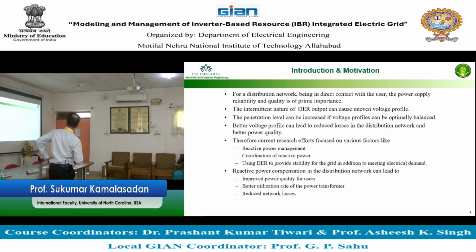Reactive power management is by and large important, for example, for the voltage profile. Now the coordination of the reactive power is also important, especially if the reactive power is coming from the same location. If the reactive power is coming from a few different locations, coordination is not important. Why is it not important? Because we say that reactive power is not global. It's a sentence which we learn. Why is reactive power not global? Meaning reactive power cannot travel from point A to point B. In transit, it will be lost, either absorbed by the inductance or absorbed by the capacitance.